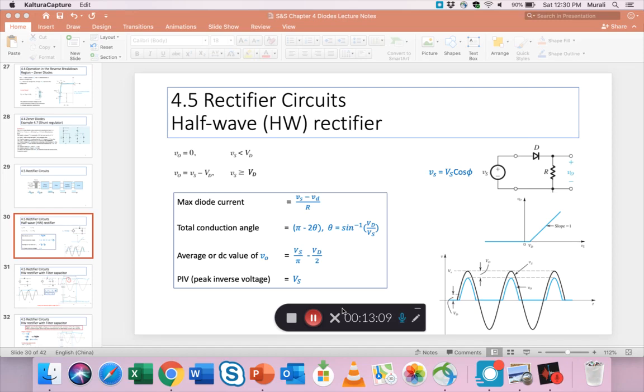With an ideal diode you can assume that it's the complete half of the cycle of the input AC, but a real diode is actually shortened even when it comes to the on time. So you can see all these factors from the figure. Give some thought to all those details shown in the graphic, because it's easier for you to just look and observe what is happening there than for me to try to explain it to you.